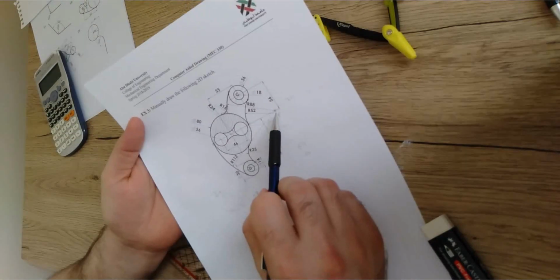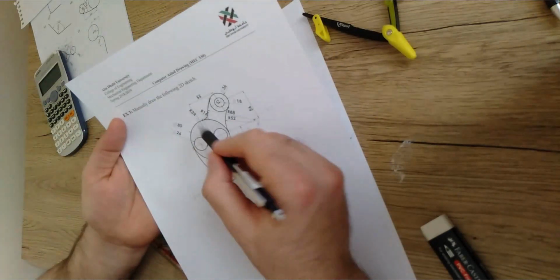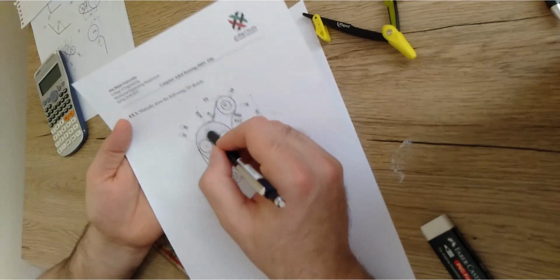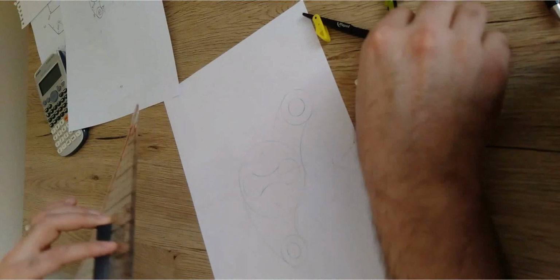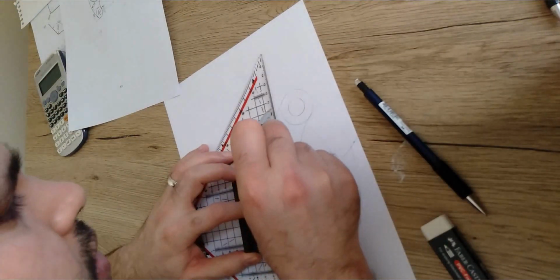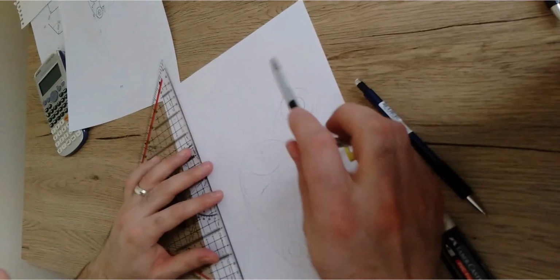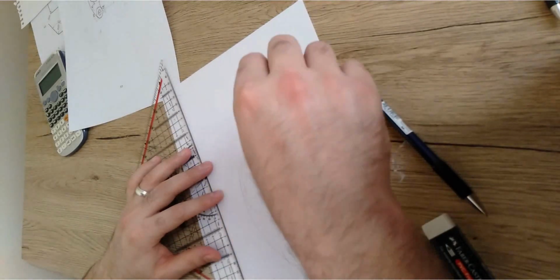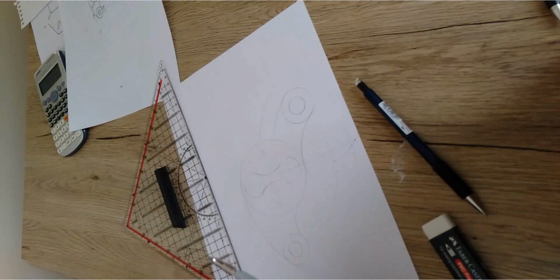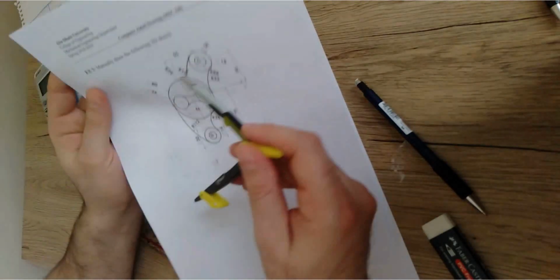So from this center point that we just located, we're going to open the cams and draw a curve with 104. This is going to give us the first locus. And this is what I'm going to do. From this center point, open with 104, then fix from this center point and draw a curve. This is going to give us the first locus of the center of the small curve R16.